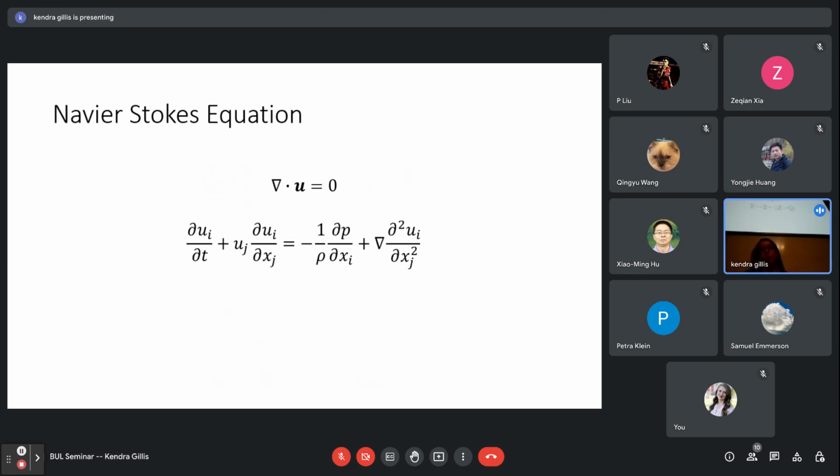The variables equal the total equations when they're all fully written out, and so we call them closed equations. If we can simulate a turbulent flow with the Navier-Stokes equations, we have almost 100% accuracy. That tells us exactly what the fluid is doing, so that would be the ideal situation if we could simulate all fluid flows using the Navier-Stokes equations.